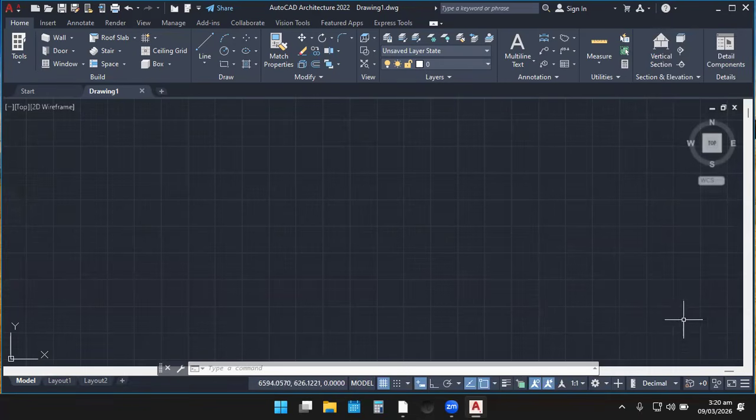So from here, what can we do? You can just put on your auto mode. F8 can also activate it. You see that it is off now, and it says restrict cursor orthogonally. So let me click it. Now you see that it is on.